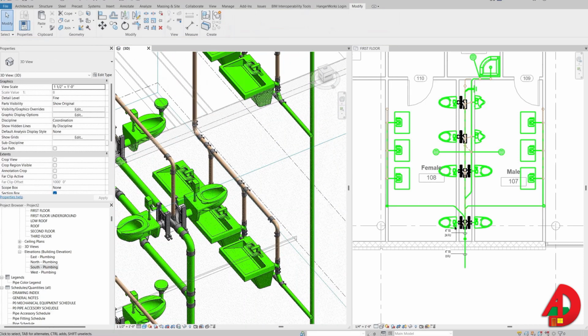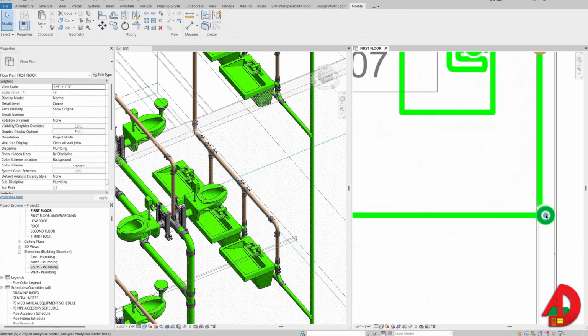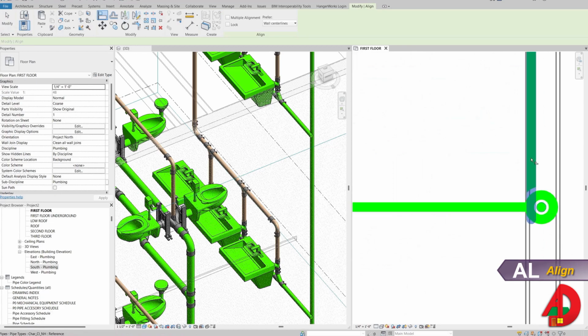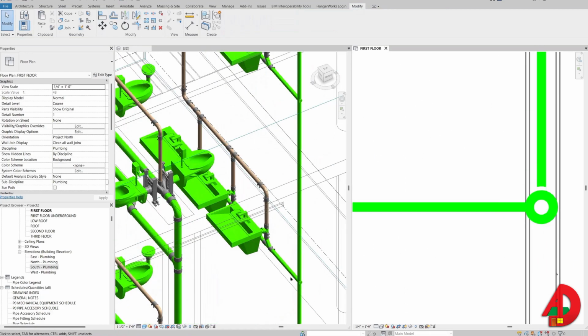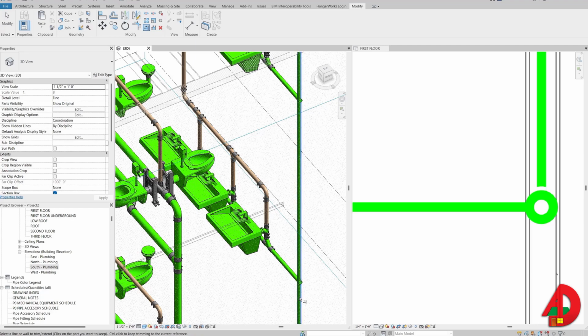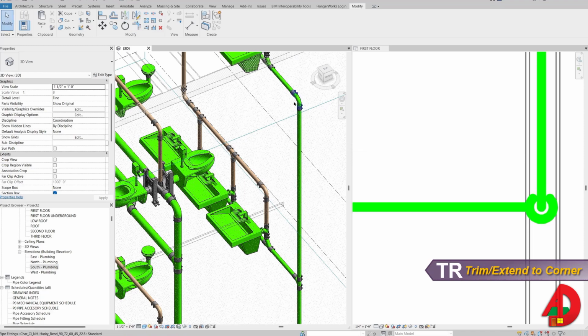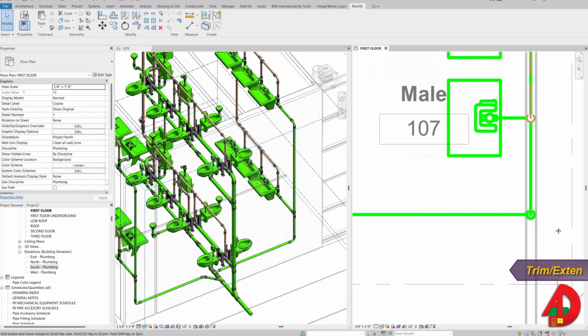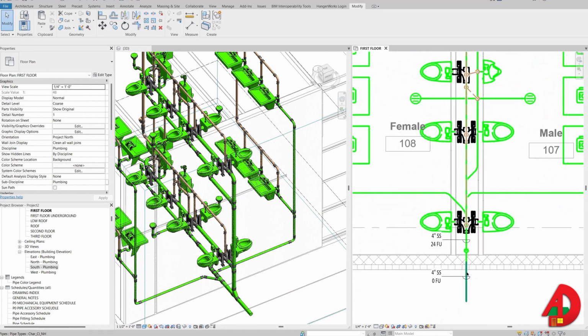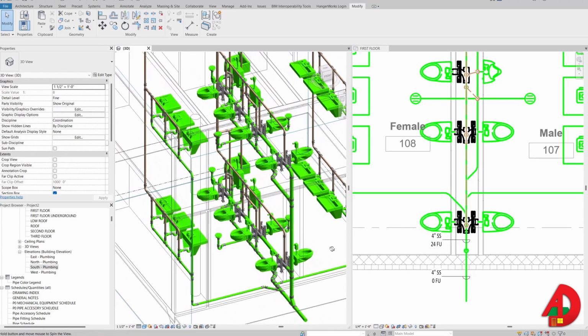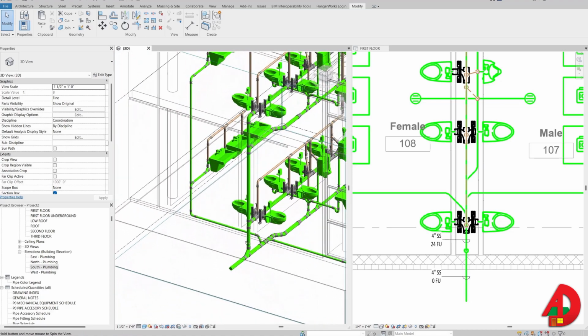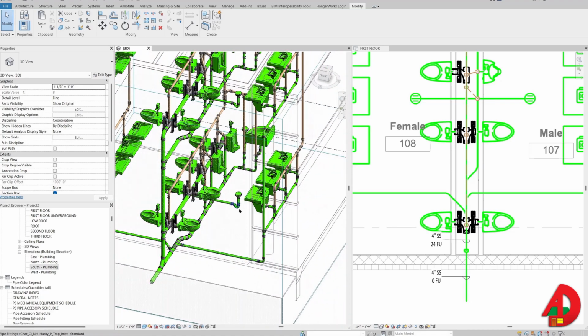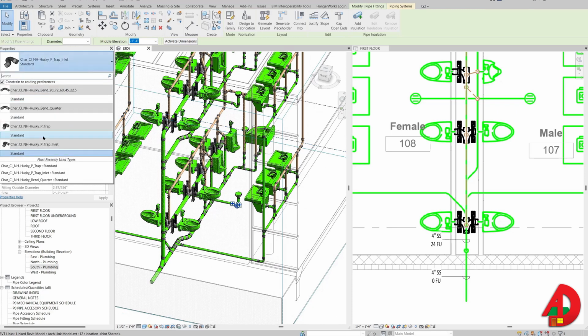And when I'm done with that, I will jump to my plan view and I can align to the center of the pipe riser. Now everything is aligned, so I can easily connect the other unconnected pipe to the riser. Total fixture units is 0 again, and I have 2 more vents that are not capped. It seems that just by replacing the P-trap for one of the drains, it will fix the system and I can see total fixture units.